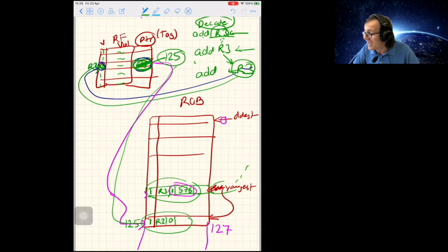What if instead of add there was a longer instruction and the next one already depends on the written register, which isn't ready yet? Do we have to stall? Yes, basically, if you don't have the value yet, you need to stall or get it out of the forwarding paths, basically.